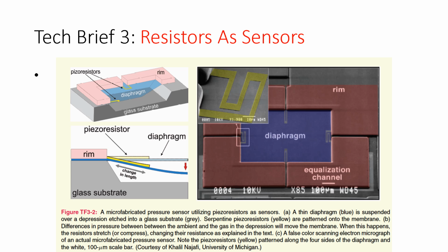However, since the change in length and the change in resistance is very, very tiny, you need a good system of being able to measure what that resistance is before and after. And you also need an amplifier generally with these too, which is something we're going to get into later with op amps. But know in general for now, the Wheatstone bridge allows you to measure what the change in resistance is to one of these. And that change in resistance matches up to a table, and that table can tell you how much pressure you're pushing on it.